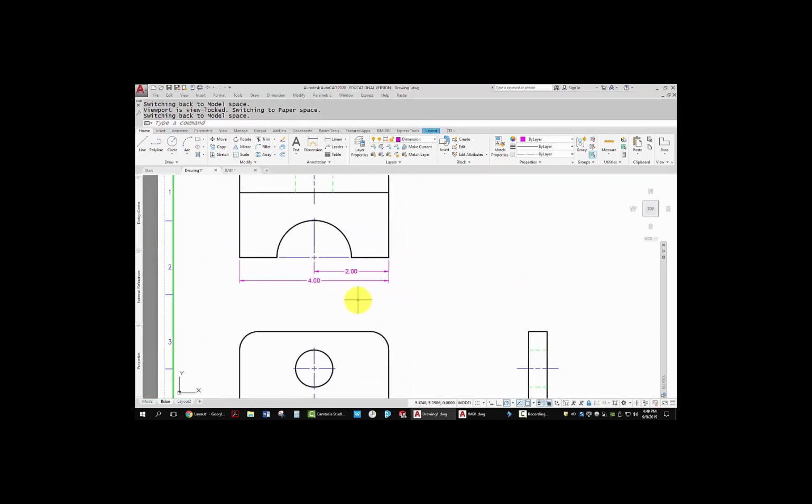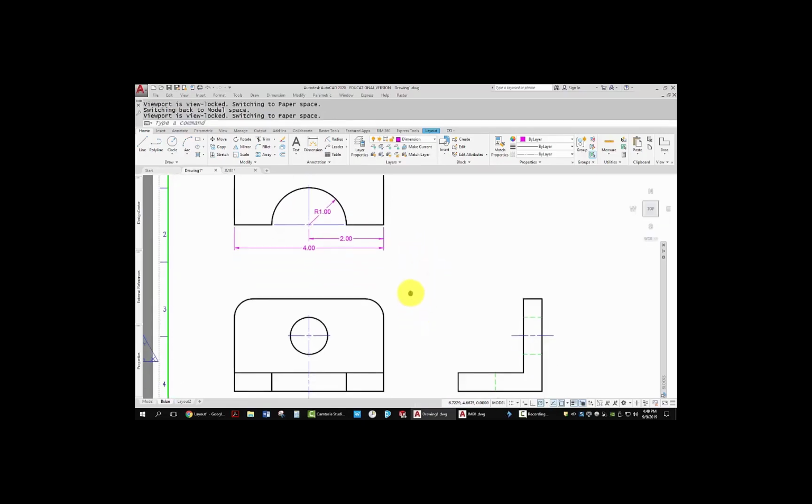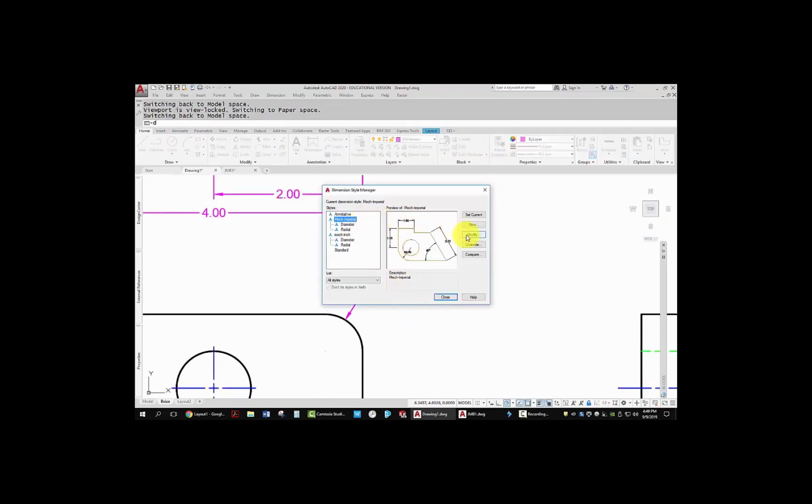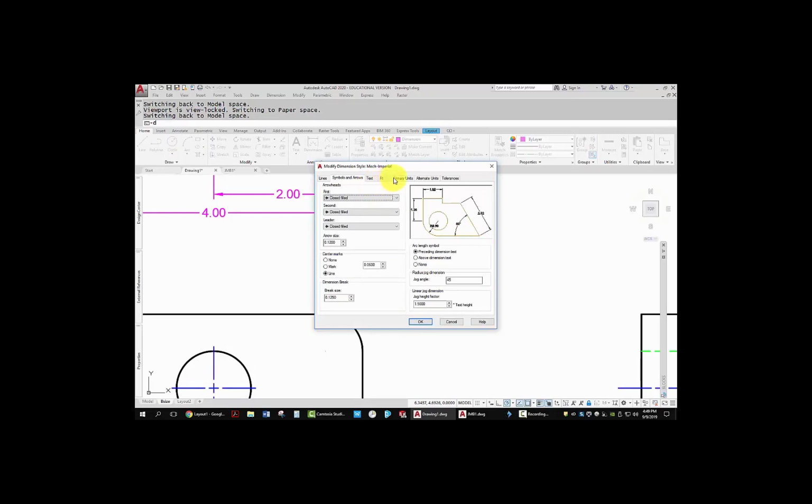Now I'm going to go back up to linear. This time I can take radial. The radial dimension is going to go in here. If you try to bring it out here, you'll discover a glitch in AutoCAD that's been there for multiple releases, where dimension in this format has to get pulled all the way out here in order to get it to look like you'd like it to look. But you can't go where I'd want to put it, which is right here. But this is perfectly acceptable as well on either side, and I can put that dimension right here. Do another radial dimension here and pull it off. And I realize that I want to make a change in my dimension style, and I will do that before you insert this. I don't want that leading 0. I'm going to modify under primary units and suppress leading zeros so that it gets rid of it like that.